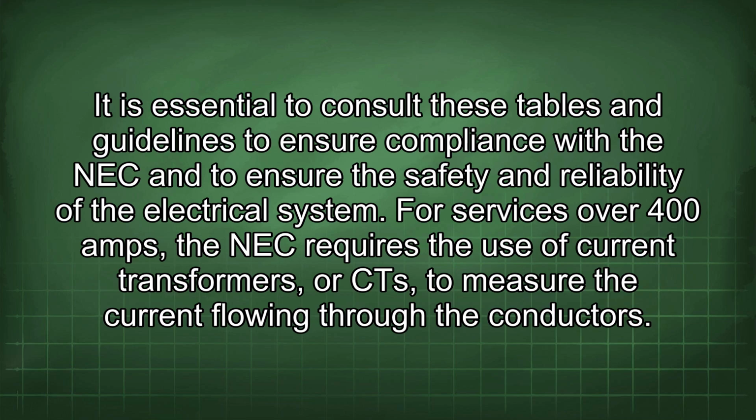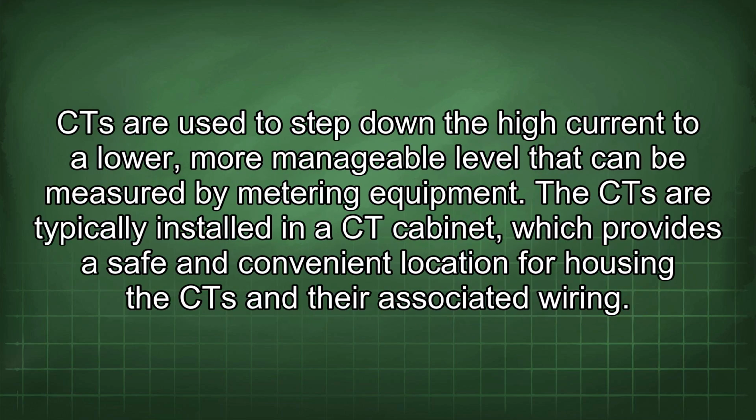For services over 400 amps, the NEC requires the use of current transformers, or CTs, to measure the current flowing through the conductors. CTs are used to step down the high current to a lower, more manageable level that can be measured by metering equipment. The CTs are typically installed in a CT cabinet, which provides a safe and convenient location for housing the CTs and their associated wiring.